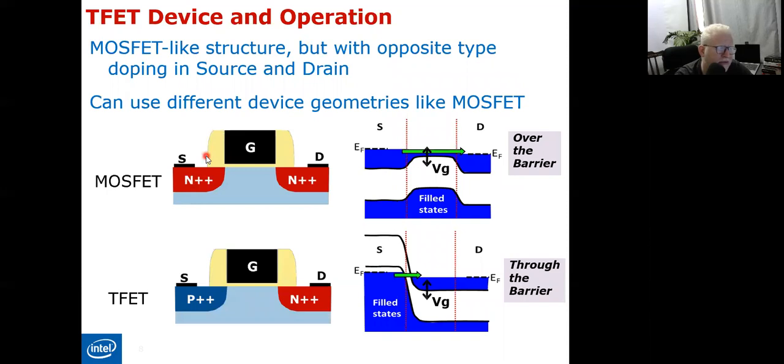So this is a very useful comparison between the standard MOSFET and what we are now introducing as a tunneling field effect transistor. Again, all these slides are captured from Intel. MOSFETs have a source, drain and substrate. Usually, the substrate has the opposite doping with respect to the source and drain. So if we have an N plus source and drain, then you have a P substrate, and this is what is represented by an N-channel MOSFET. Here we have the gate oxide and the gate, and this is a three-terminal device as we already studied. And actually, this is the energy band diagram corresponding to this structure.